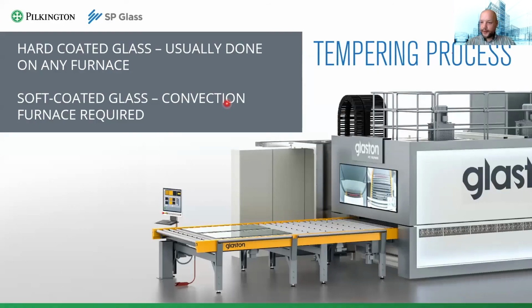Let's move on to the tempering. And there we encounter the first real obstacle, because your tempering furnace has to have convection in order to temper a soft-coated glass properly. Soft-coated glass, again, usually has low E properties, and without the top convection furnace, you will not be able to temper it properly. So it will have visual defects for sure.